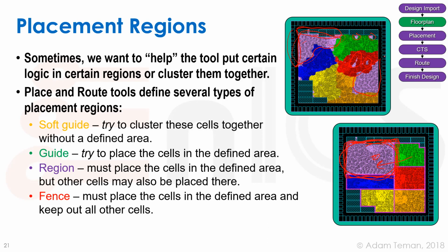On the other hand, probably these IOs, they talk directly to these purple areas, so they pull these cells over to here. I imagine that these little islands are kind of places that help us buffer and talk between these regions that probably have several paths that move together. And maybe some of these RAMs are also part of the purple region. So it would be better to fix our floor plan if possible than to actually region out and make the tool do something that may be suboptimal.